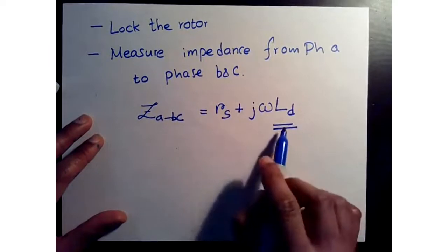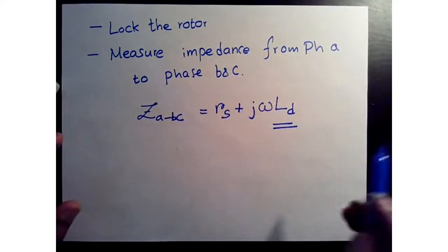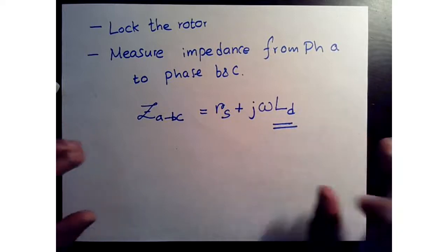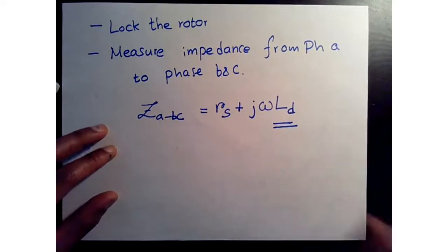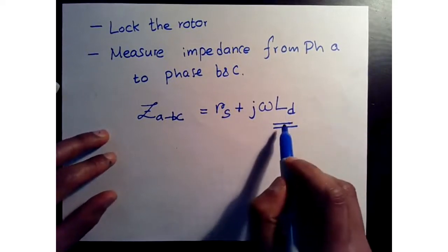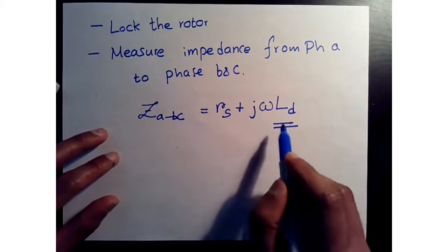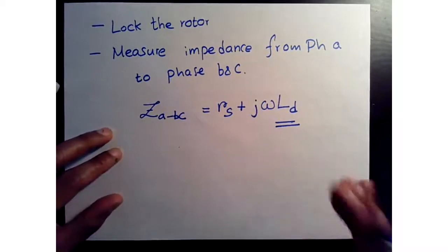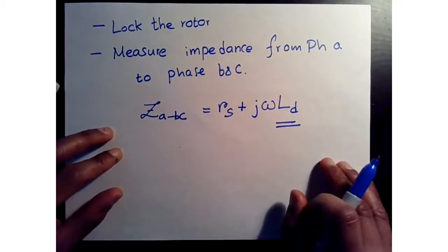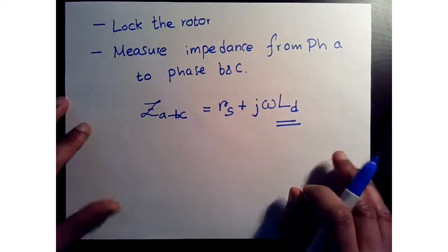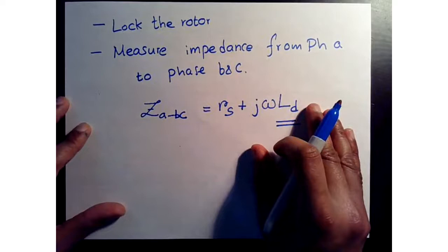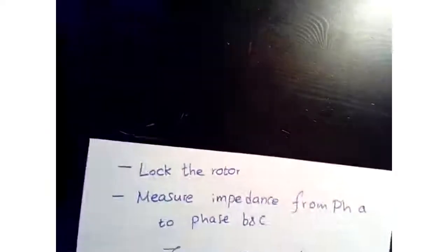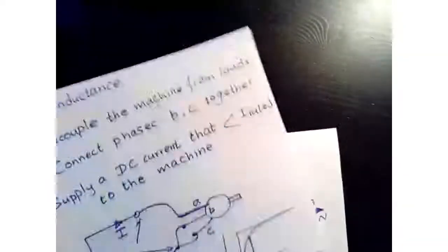So you can measure it in a couple of different methods. You can apply a high current step and measure the time constant, or there are other sinusoidal injection methods to measure the inductance too. That way you can obtain the inductance at a certain frequency rather than the time constant or the steady state value. We can do that at different frequencies. So now this will give you your D-axis inductance. Very convenient. So we have our D-axis inductance.